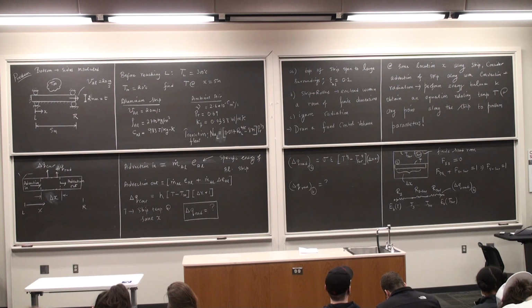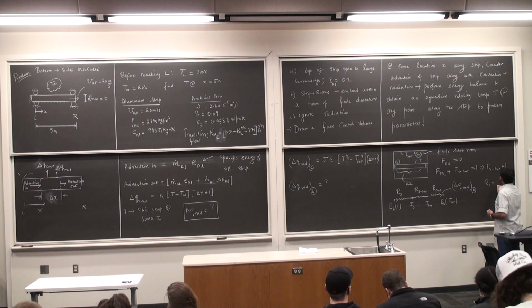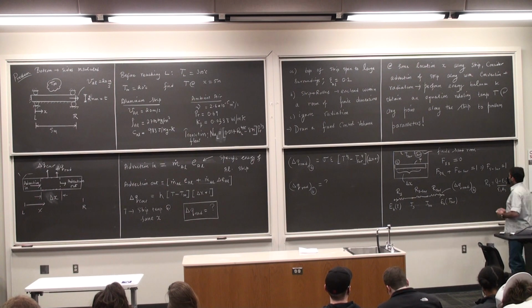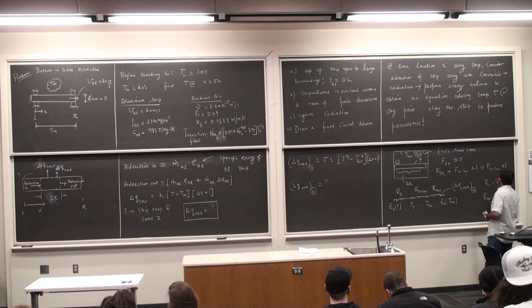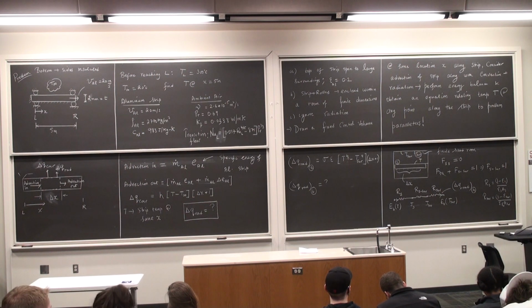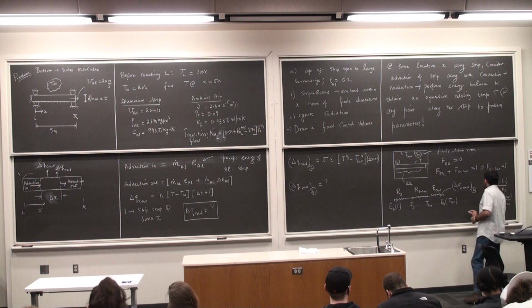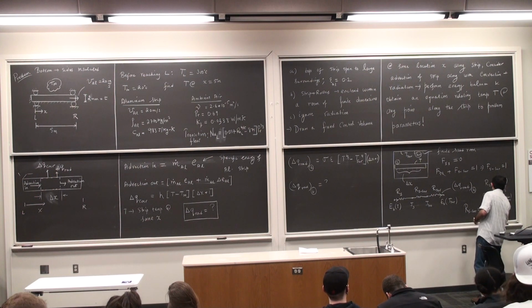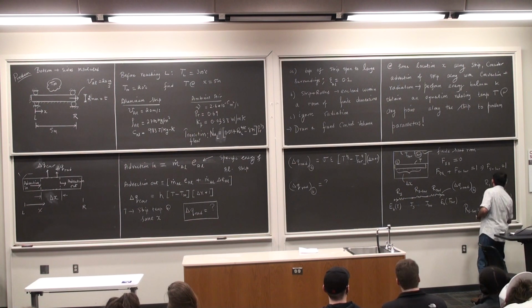And if I have to list all the resistances, R_S is 1 minus epsilon S divided by epsilon S times A suffix S. Then R surrounding is 1 minus epsilon surrounding over epsilon surrounding times A surrounding. And then the last one is the geometric resistance, R_S surrounding is 1 by area of the surface times the view factor.